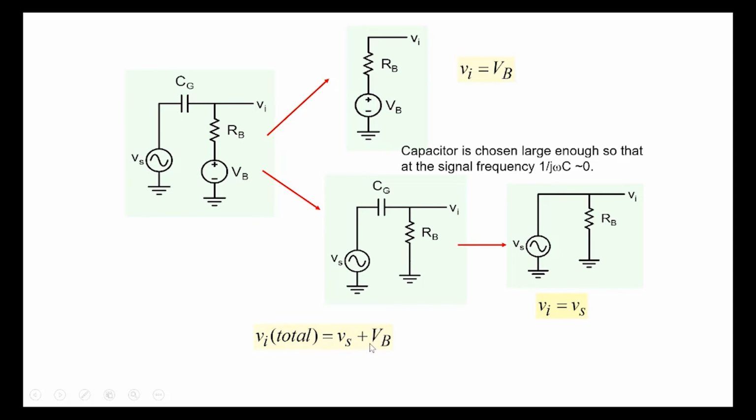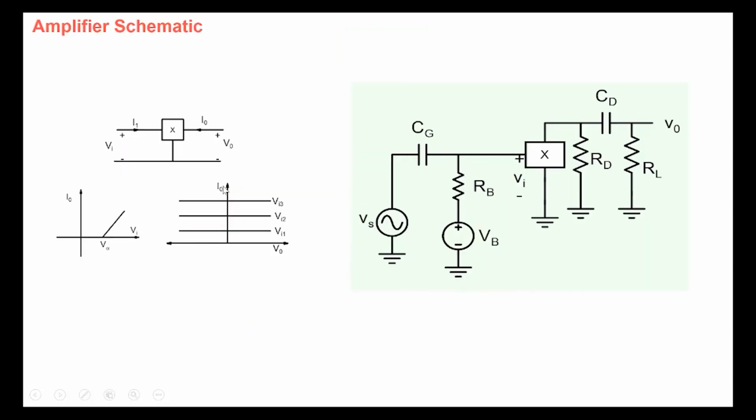So we are able to sum the bias voltage and the sinusoidal signal through this means when one terminal of each, or both, is ground. Note the importance of RB. Even though no current may be flowing through RB in this particular case, RB is essential. If you don't have RB, then think about what will happen. So the biasing resistor RB is essential here.